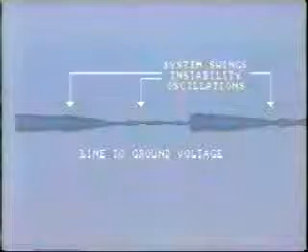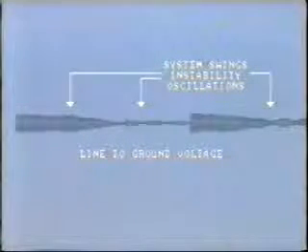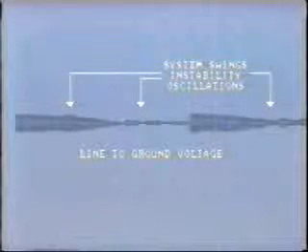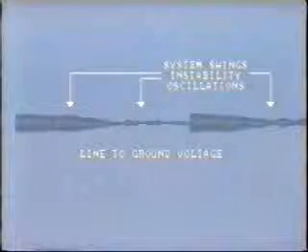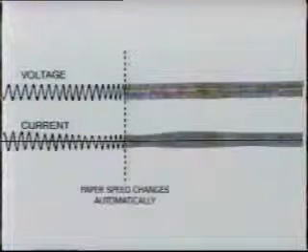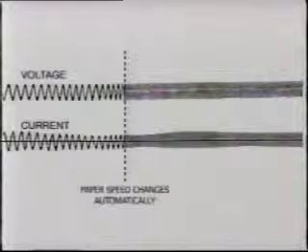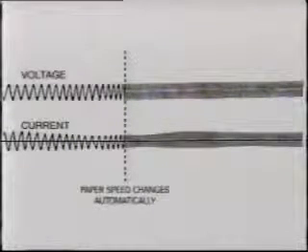We have been looking at oscillograms associated with faults on the system. Generally, the whole story can be shown within a few cycles, usually less than 1 second. System swings, such as those associated with instability, can also be recorded, but such swings may last for several hundreds of cycles and consequently give us a lot of paper to examine. Some oscillographs have the ability to change paper speed automatically when recording these longer-term swings.